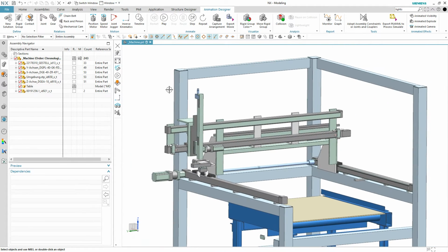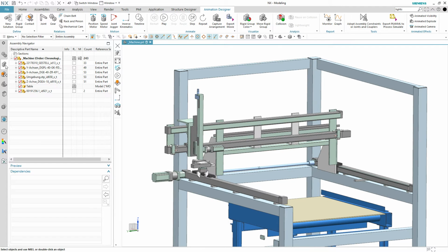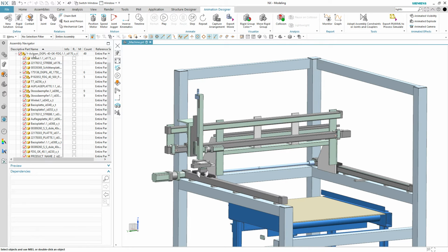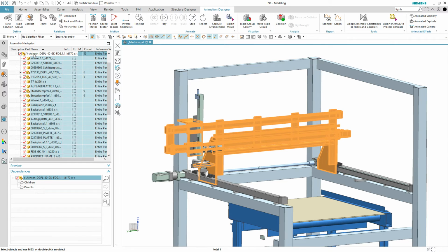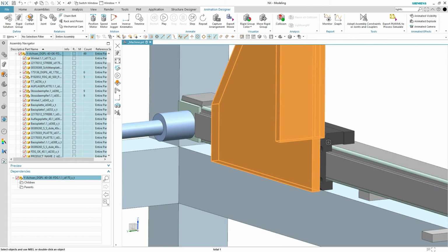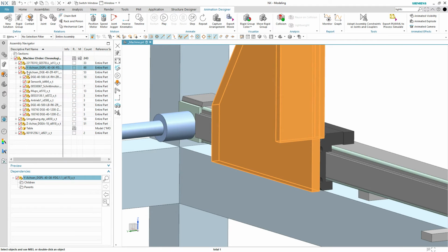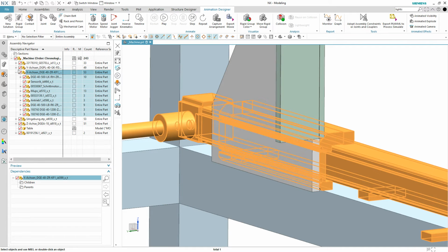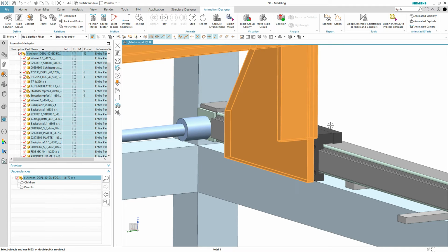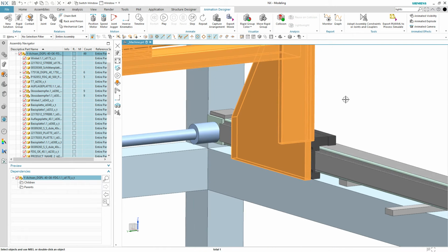What we're going to do is first, I recommend going to the Assembly Navigator and expanding the second and third subassemblies. That way you have a nice fast way of picking things. Here's the problem: whoever built the assembly forgot to include these little feet in the highlighted subassembly. They put them in a completely different subassembly, and while it sounded good at the time, it doesn't lend itself to good motion because we want these sliders to go along with this transport mechanism.